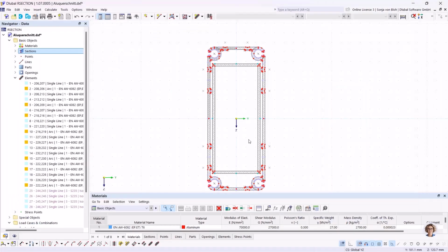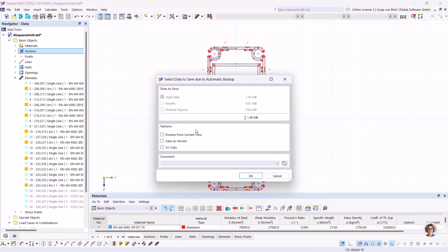on OK. Only cross sections that are rigidly connected to each other can be imported into RFEM 6 or RSTAB 9. This connection is applied over the entire length of the member. If the cross sections are not connected to each other, the modeling presented here is not suitable. Two members would then have to be created in RFEM or RSTAB. As I mentioned at the beginning, I will also show this today.